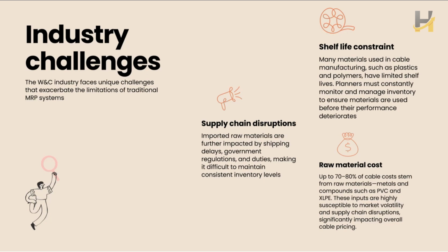Let's suppose you are able to manage these costs. They are further amplified if the materials are imported, and there are supply chain uncertainties: shipping, logistics, government regulation, duties, and their timely availability as well. And the third is this: even if you have all of these things in mind, and you have these materials in place, a third constraint that comes in is the shelf life of these materials, specifically the polymer derivatives. They have their own shelf lives, and if they are not consumed within that shelf life period, there is a very high possibility that the quality of the product and its performance starts deteriorating, which will have an impact on the cable.